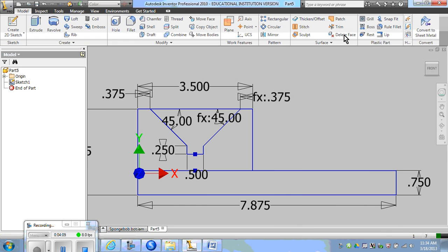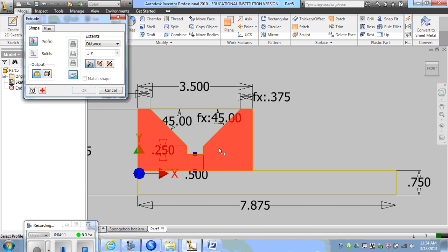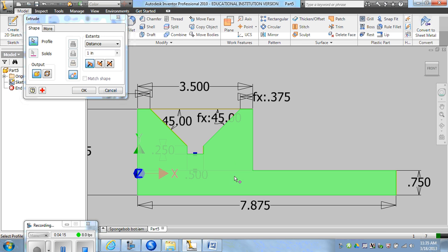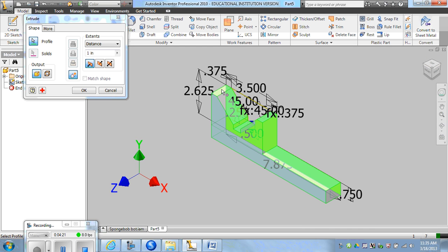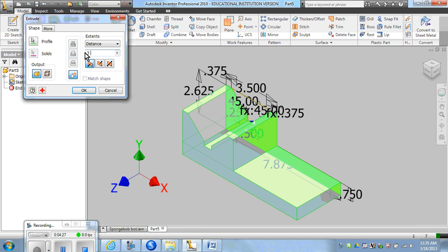After we're done all the dimensions, we should be able to extrude. Finish sketch, extrude. I have to click on multiple parts to make sure I get what I need to extrude. Extrude these boundaries here. And the shape is 3 1/4 wide.